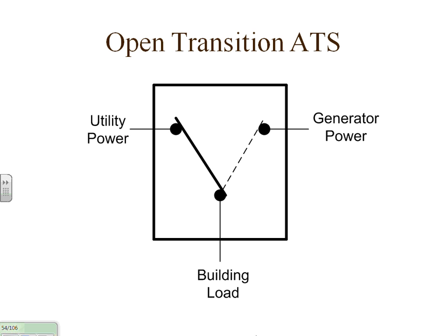The second one is once the generator's running, it's kind of an optional time delay. It's the least critical. We'll give it just a few seconds to run unloaded before we hit it with load. I'll interject to Chad's point earlier. In this situation, this is a non-legally required.